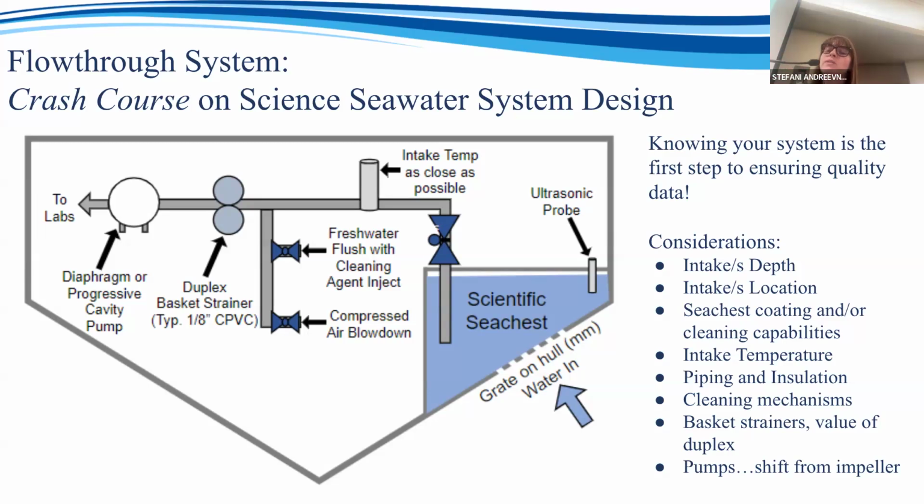Sea chest coating and cleaning capabilities of your sea chest, intake temperature, what, where, how, piping and insulation, cleaning mechanisms either within your scientific sea chest or within the piping itself, basket strainers along the way. How many people have basket strainers? How many people have duplex basket strainers?